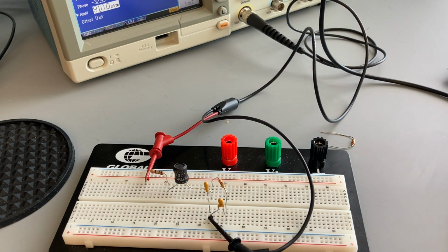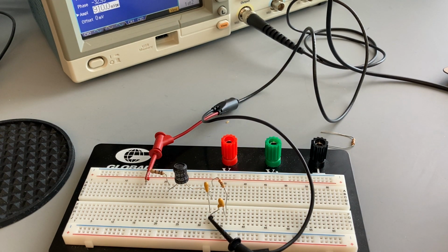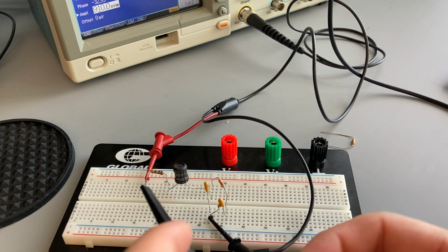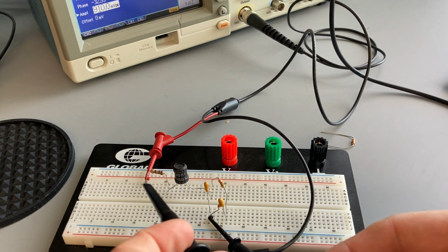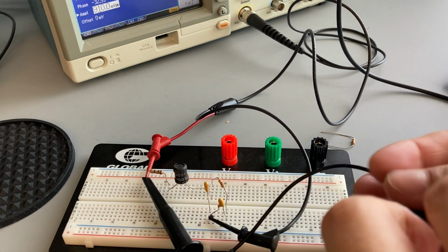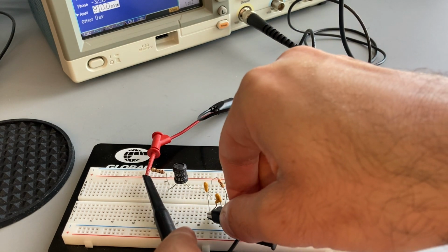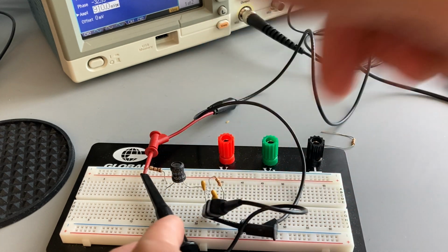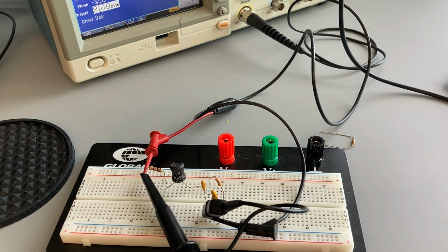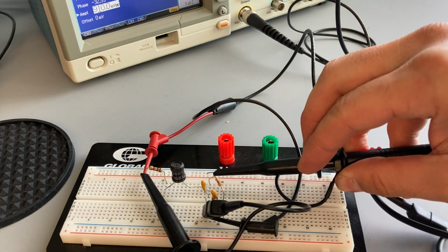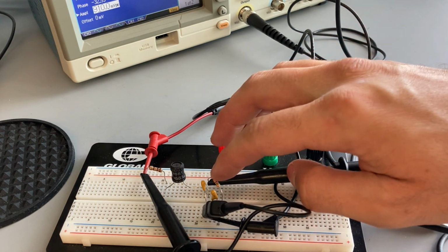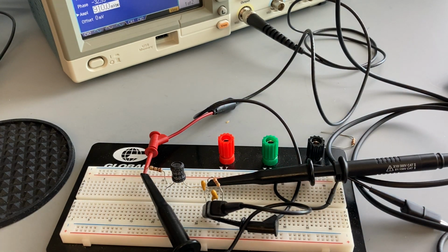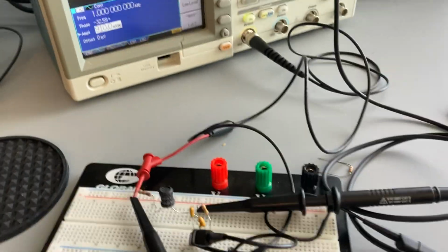I'm going to place the probes the same way, because I want to determine my voltage across the entire circuit. I'm going to place this oscilloscope probe across the entire circuit and connect a ground clip to this leg. A little tight, but it'll work. Then I'm going to place one probe across the load. Then we want to switch on our output.